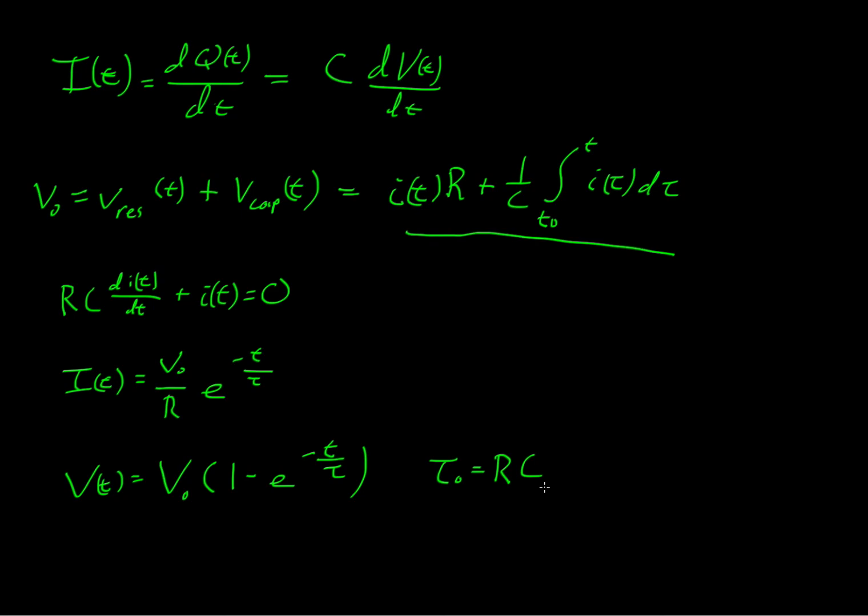As the capacitor reaches equilibrium with the source voltage, the voltage across the resistor and the current through the entire circuit decay exponentially away. Okay. In the case of discharging a charged capacitor, it likewise demonstrates exponential decay, but with the initial capacitor voltage replacing your source voltage and the final voltage being 0.